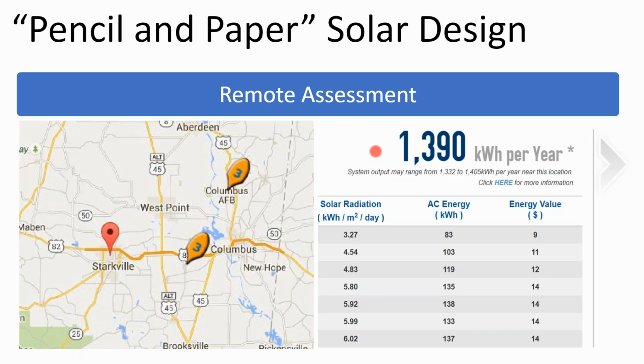So if you're designing an off-grid home and you're using PV watts as your example, you might be thinking your design is really conservative because you're basing it off PV watts data and planning for X many days of storage. But if a hurricane rolls through, you might get more cloudy weather than typical. PV watts models typical local weather.